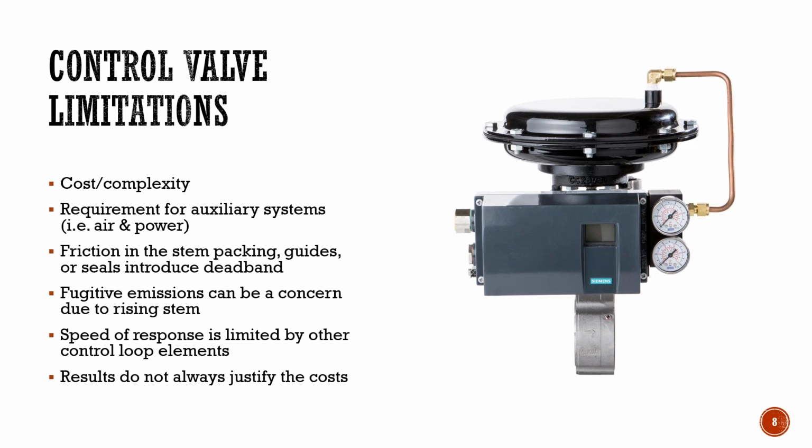Speed of response is limited by the other control loop elements. So even though the time involved is extremely fast, it is slower than some other options that you may have. And the results do not always justify the costs. So what we're going to explore today is, do you need a control valve?